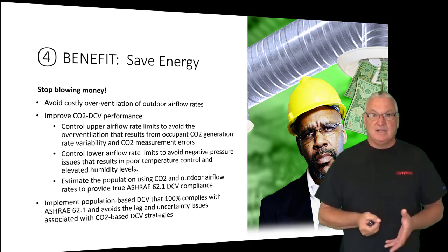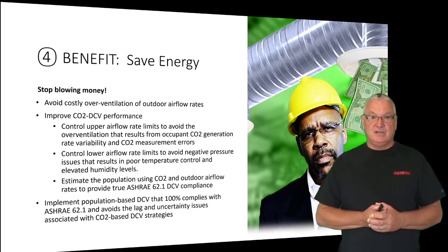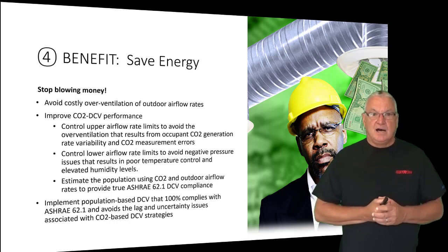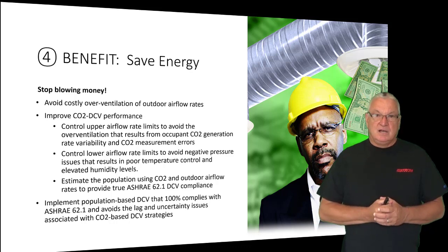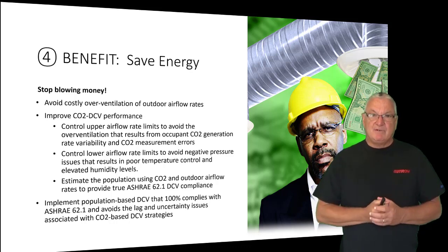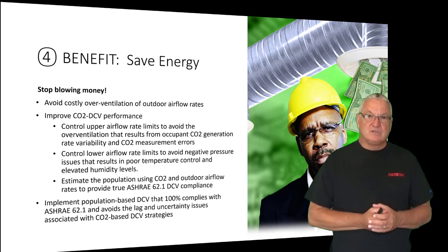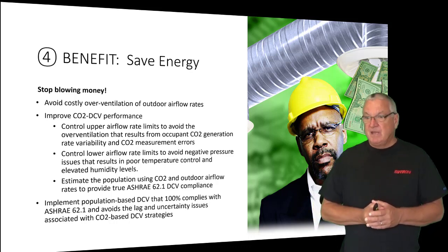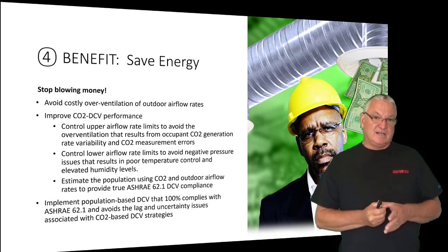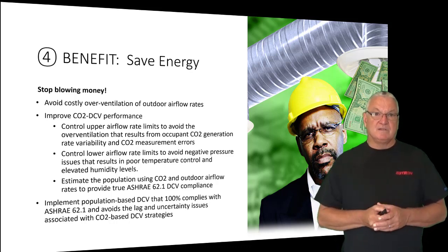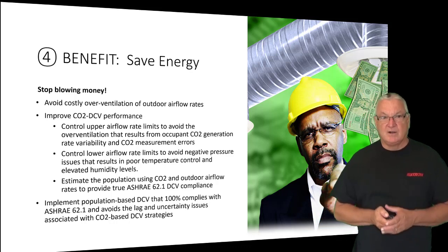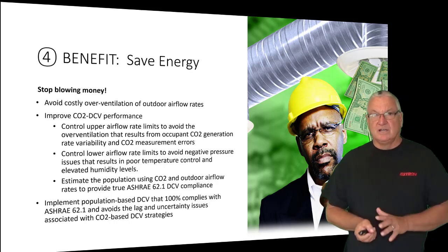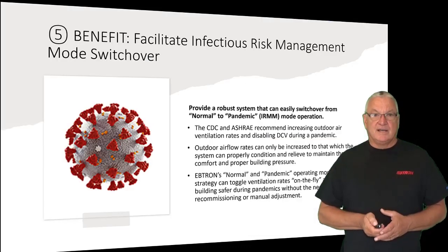Again, I can't get into it in any detail in this short presentation, but I think it's very useful and very important for people to understand. I also think there's a valuable discussion we can have about why we are measuring CO2 in the first place when what we really care about is the dilution ventilation. Maybe we should be setting these dilution ventilation rates based on measured occupancy. So we have nice presentations there. That all falls into saving energy, but I could also put that into improving indoor air quality. It depends on how you want to look at it, okay?